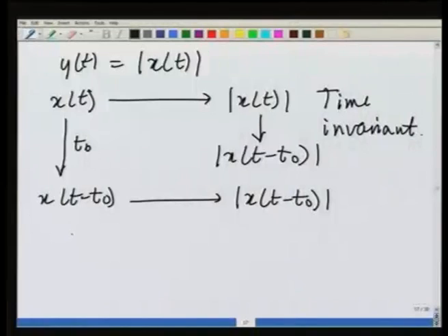So, for the same voltage, the same capacitor will store less and less charge as it gets older. After a long time, you would probably find that any electronic circuit begins to malfunction because its components age. So, this aging is one manifestation of time varying behavior.